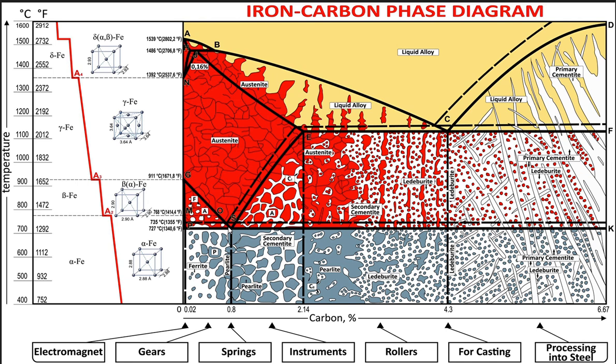And then let's talk about steel versus cast iron. The difference is this vertical single line. It is what parts steel and cast iron. If our iron has less than 2.14% carbon, it's steel. If it has more, it's basically cast iron.